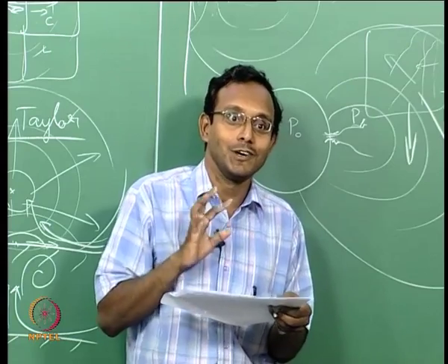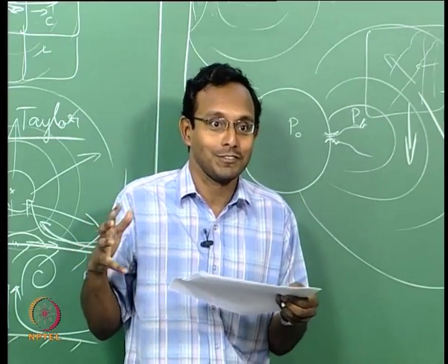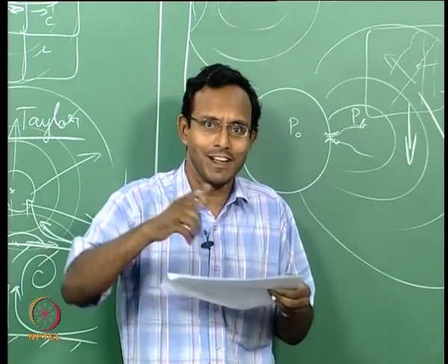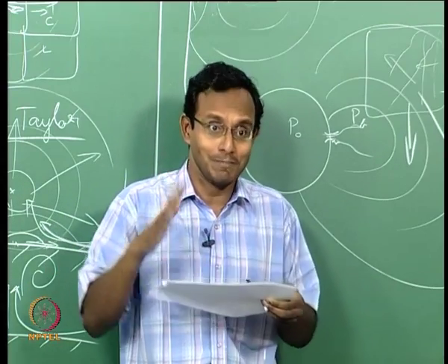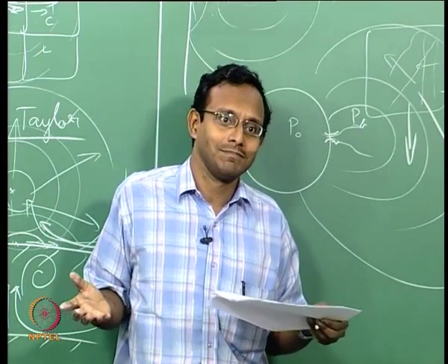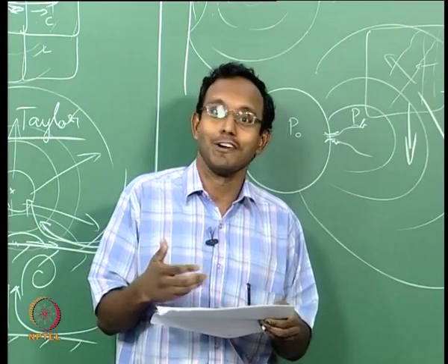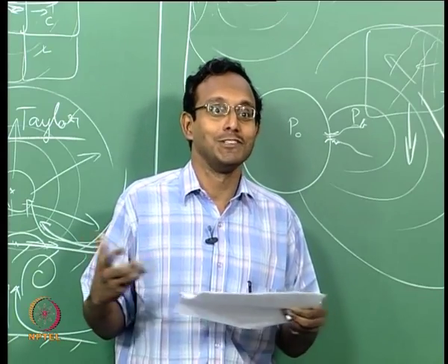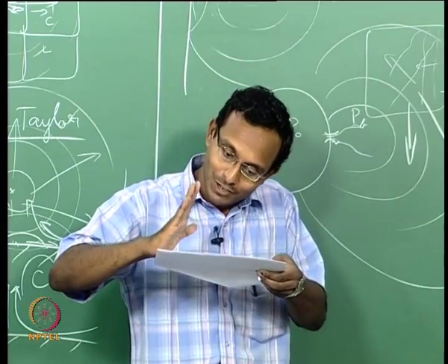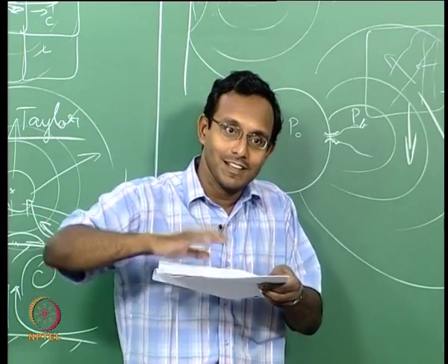Okay. This is your unsteady flow phenomenon I am talking about. This is all fully compressible flow. I do not care what speed it is. In fact, I will show you an experiment where we measured the actual velocity at which it is going and hitting. It was 6 meters per second, and we can see a shock in front of it. That is very easy to think about, 6 meters per second creating a shock. Anyways, so it is going and hitting like this.